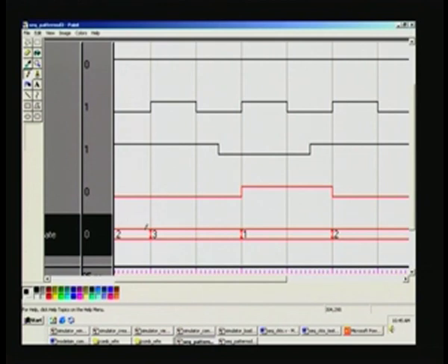So, the state itself is changing at this positive edge. Its corresponding output will get reflected only here, because it has to wait for entering the state only at the next positive edge. It has just entered the state, right. That state will be processed only at the next clock edge. Only after you process that particular state, you can get the output. That is why it is happening. Are we clear with this? So, I explained earlier.